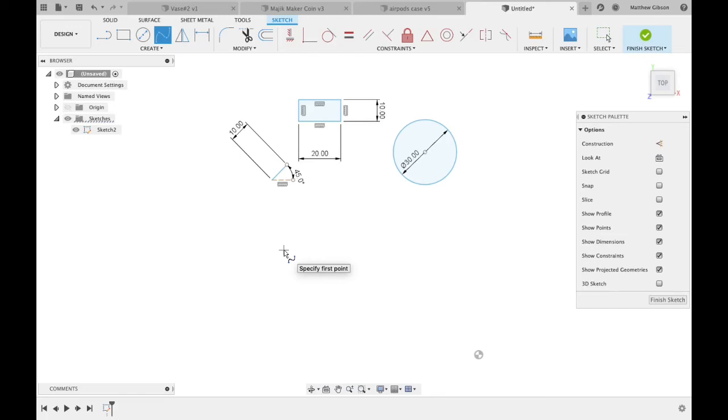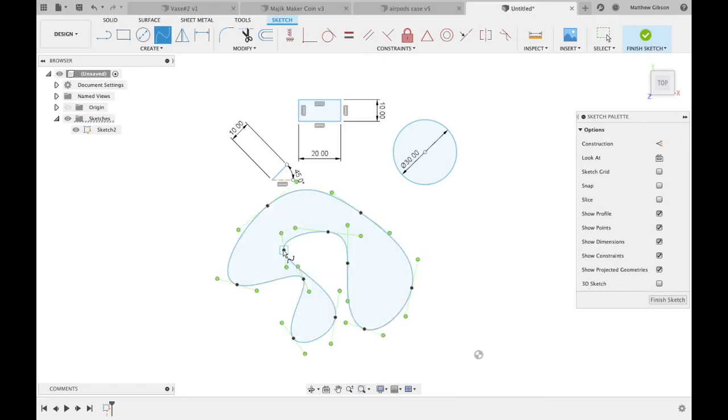So after you select spline and you left click, you can drag, and you'll see a dot and a line wherever you drag. Now, once you left click again, don't click the check mark. But if you keep dragging, you can see that it creates a curve. And if you keep on doing that over and over again, then just connect them again, it will create an odd looking shape, which would otherwise be impossible with just a straight line.